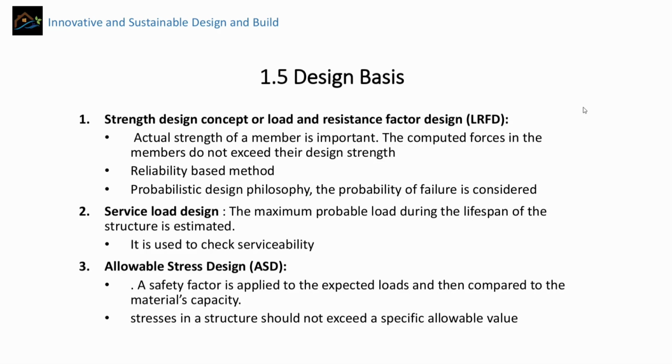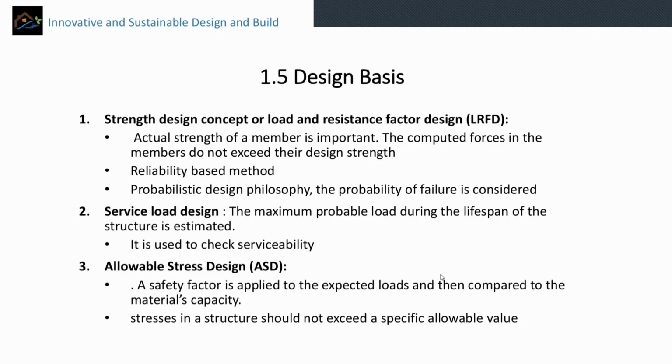It's basically when we build a bridge or any structure, and then we define the maximum number of people that should use it, the maximum axle loads, and therefore we should take care of the users and the loads that are imposed on the building. And these loads should not exceed a specified allowable value that we determine for the building.